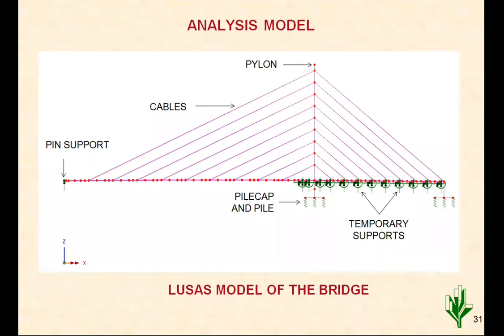Suppose we have estimated a deck erection crane of 180 ton, and because of some fabrication issue or something it becomes 200 tons, and 20 ton is increased, then 20 into 124, that much is the moment increase on the overall system of this pylon. So the load estimation has to be very precise, and all the load cases of the stage by stage construction sequence have to be monitored.